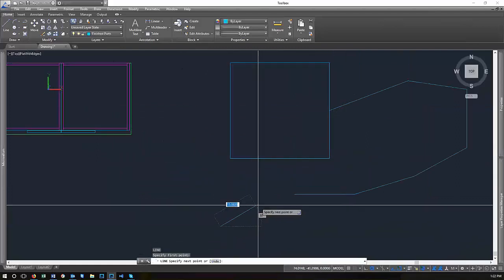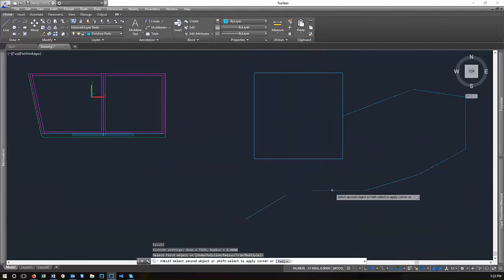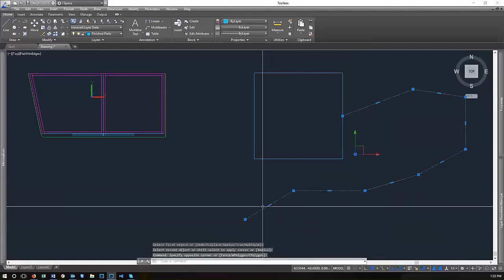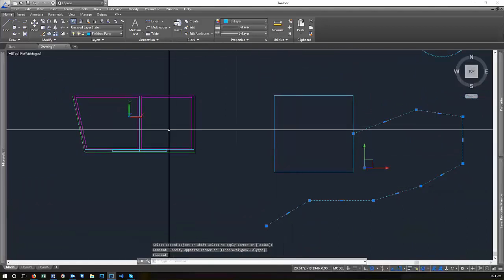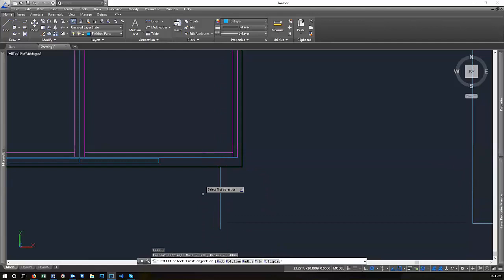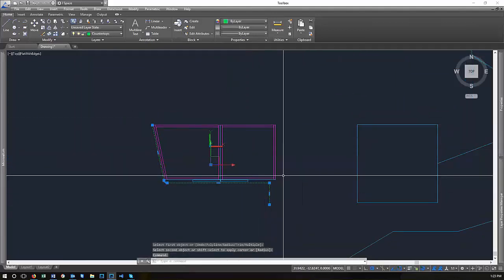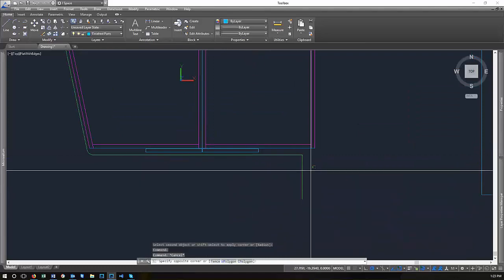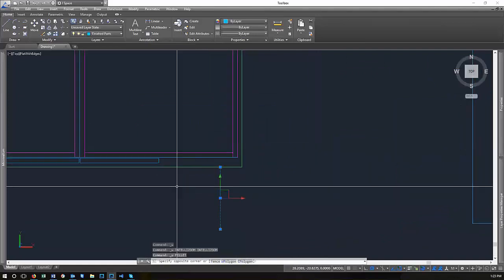If I say I want that here, this is a polyline, that's a regular line. If I fillet the two of these with a 0 or even with a curve, it will join the polyline to the regular line. So that's a subtle difference, a slight difference between the way they interact. If you fillet between these two, it eliminates that section. It cuts the line wherever the start point for that line was. So you want to be careful when filleting between entities, whether it's a polyline or a regular line, because it does react differently. Okay, so erase that.